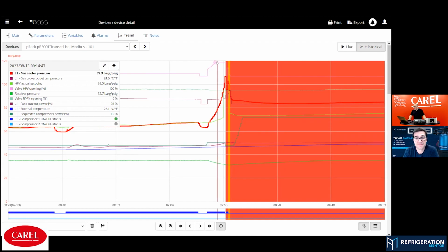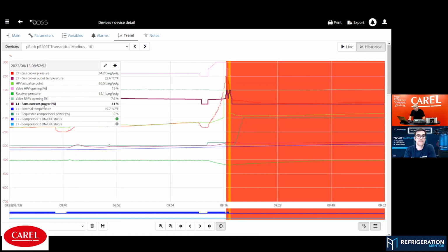So you have different things you can take a look at. Is the fan from the gas cooler running? We see it here more or less in our log graphs. It is running. There are different indicators you can see. On the one hand, we have our fans, here the current and the percentage of our fan speed, 33%. Oh, that's cool. So we know the fans are running.